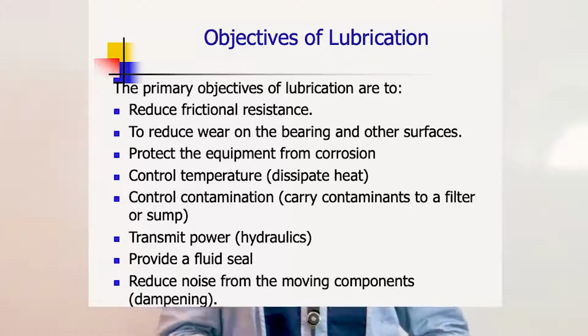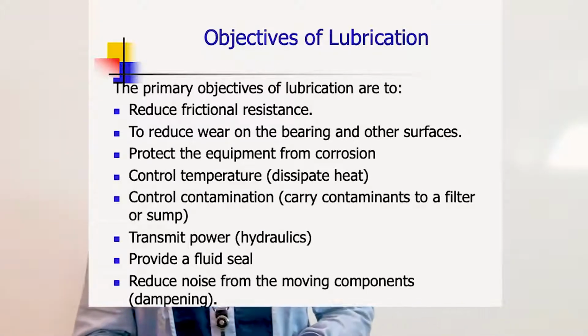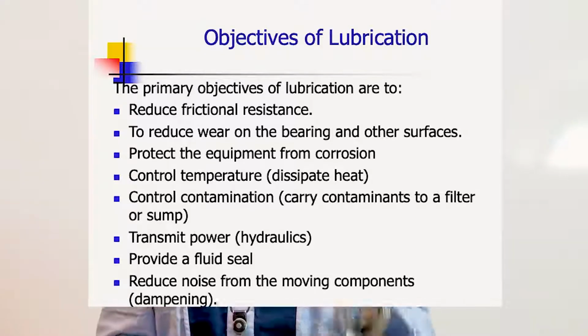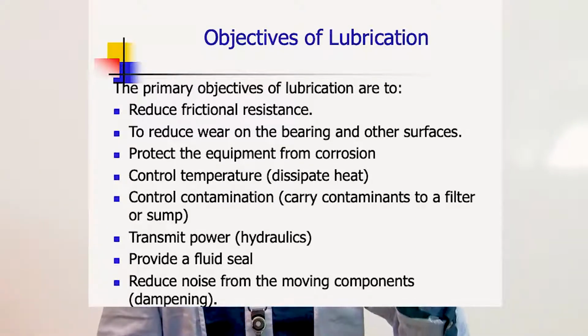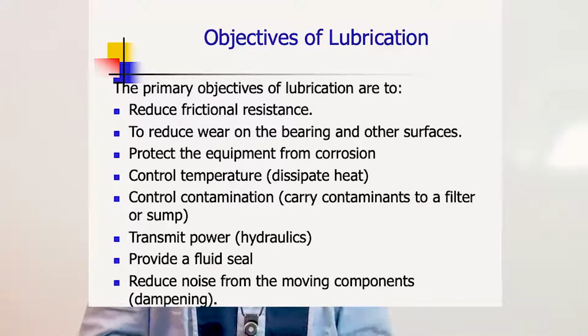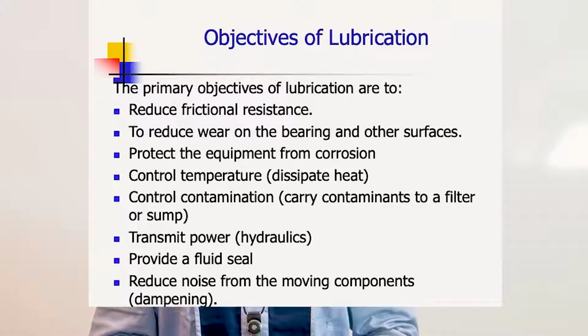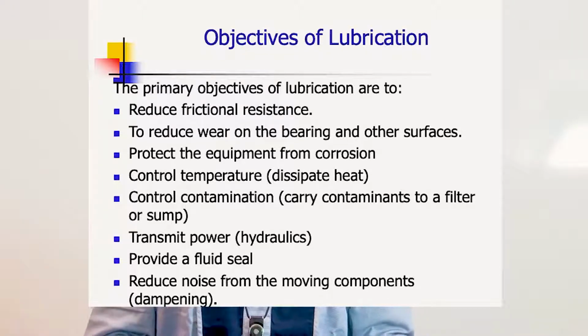What are the objectives of lubrication? The primary objectives of lubrication are, number one, to reduce frictional resistance, bring friction to the barest minimum, if at all you cannot completely eliminate it. Number two, to reduce wear on the operating and other surfaces.